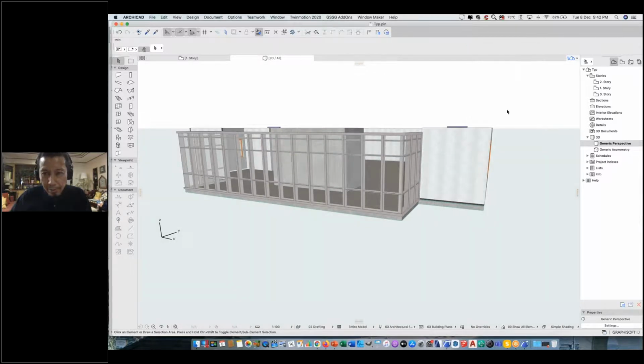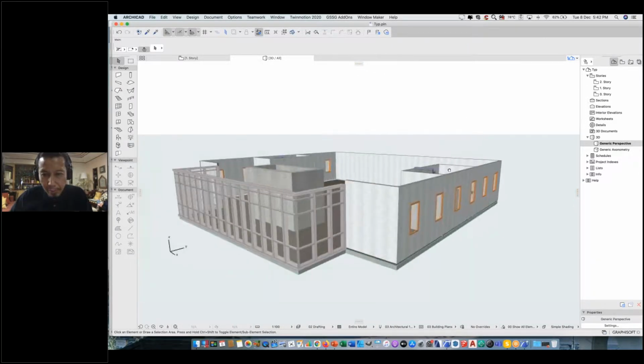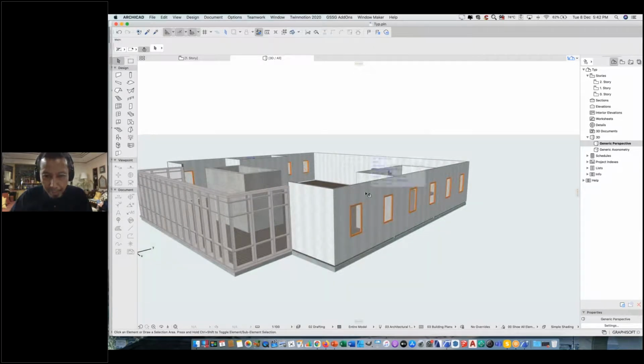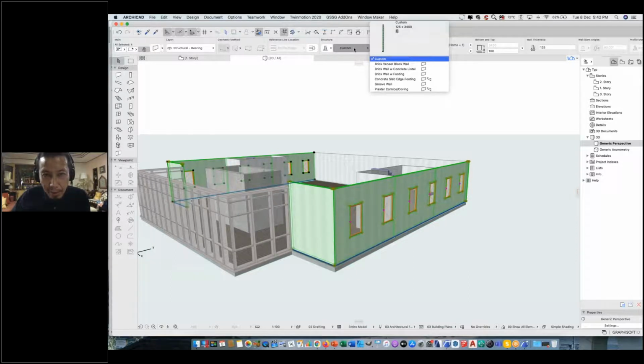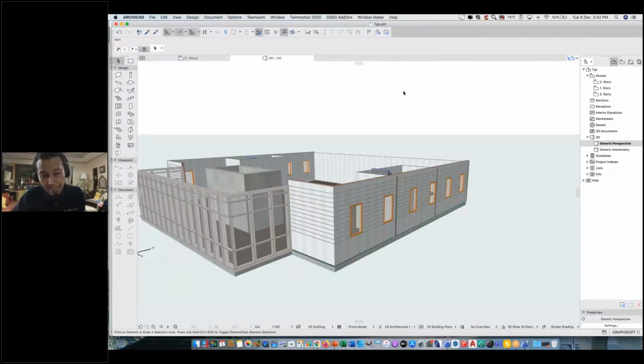Okay, let's close this. Maybe this wall. Maybe I suspend the group. I just want to make this wall, and I'm going to change this wall to even. The other side also, so I can select that wall together with this wall, and I'm going to change this to a complex profile, and use this as groove wall. I'm going to replace it with my groove wall.